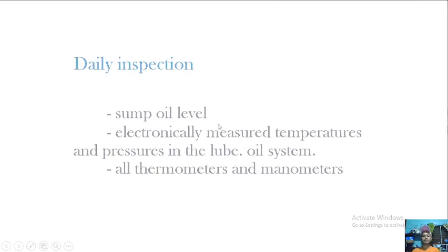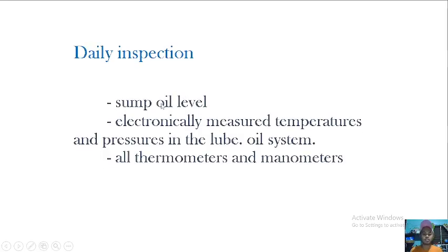Okay, so what are the daily inspections? Sump oil level. You should always check the oil level in the sump tank. And then the electrically measured temperatures and pressures in the lube oil system. Check the electronically measured temperatures and pressures, and also the local or manual Bourdon tube temperature and pressure gauges, and all thermometers and manometers. So these are the manual ones.